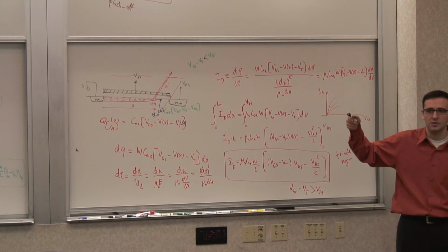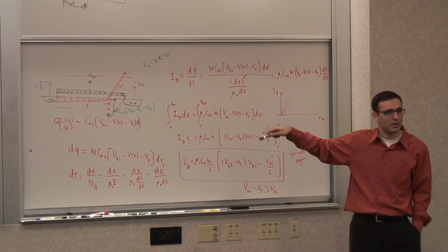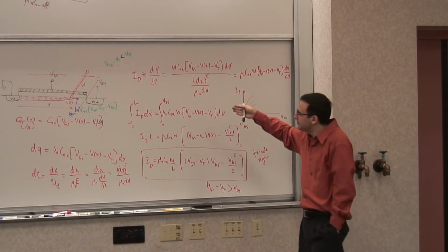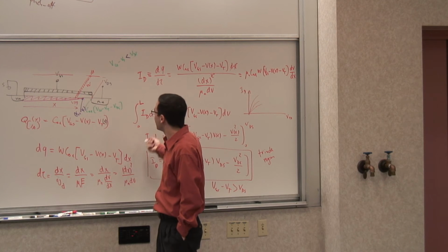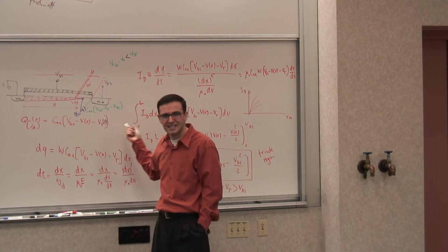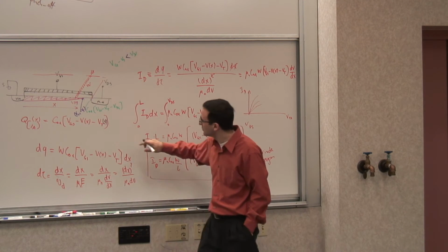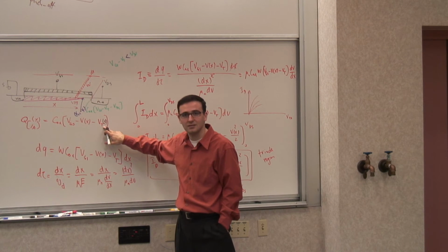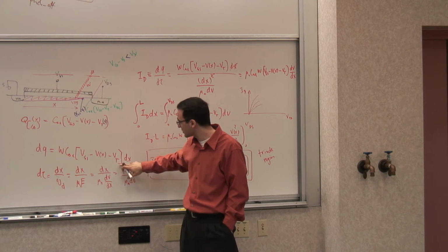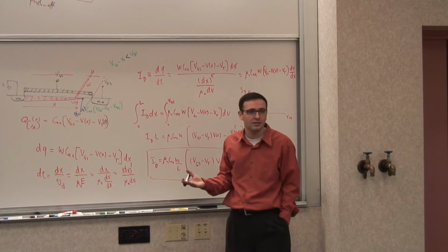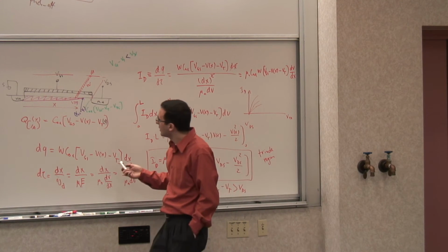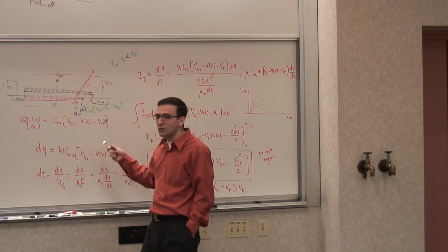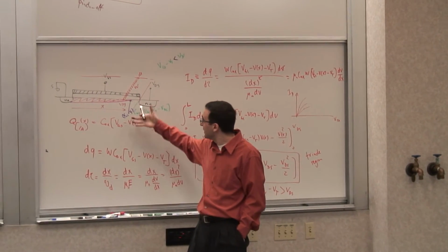If you're interested, I can give you some references on the calculations. You can go and look it up. It's a longer derivation, right? It's nothing fancy. It's basically essentially the same thing. Just you take into account the fact that VT is a function of x, and then you put that functionality in this integral, and then you integrate it. That's the bulk charge theory, and you can come up with expressions.